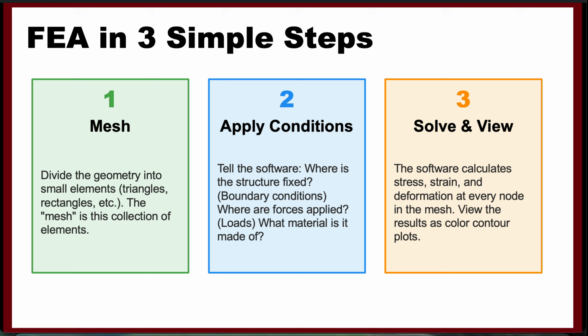And then we apply conditions. We essentially tell our software where the force is being applied, where the wall is, and what is the material that is being used in the beam, and so on and so forth. And eventually we are going to solve the problem using the exerted force and calculate the stress, strain, and deformation at every node in the mesh.